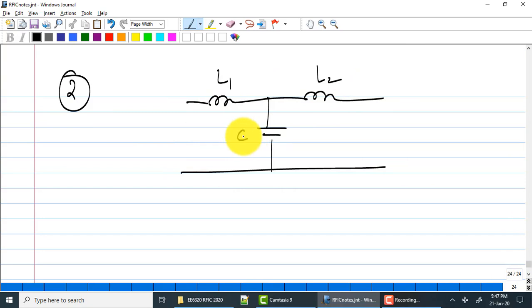Okay. And find out if L2 is larger than LL. Right? So basically what you are trying to do, you are trying to match to the real portion. Okay. And then moving the portion from that inductance and moving it into the load. So you have basically made the problem into matching real to real, except you are now, whether you count the inductance with the load or with the matching network is all that matters. Conceptually it doesn't matter. Okay?